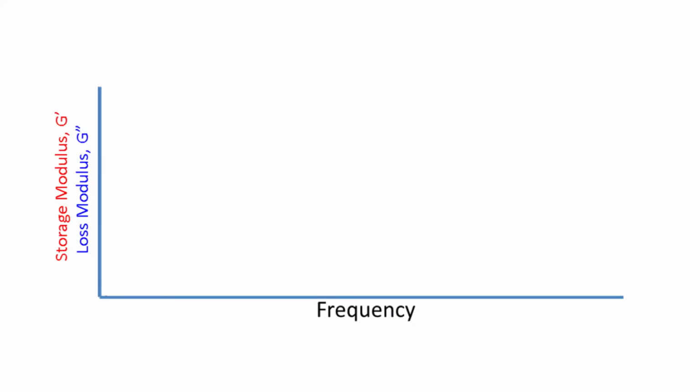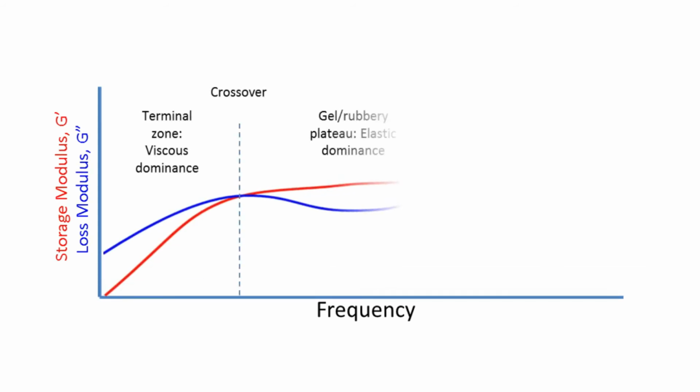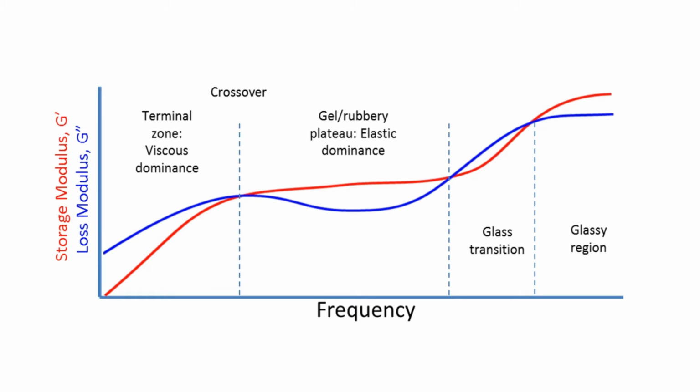So the regulatory bodies request storage and loss modulus versus frequency. In the test, the sample is oscillated at a range of frequencies, effectively imposing a range of deformation timescales on the sample. The reason they do this is that by assessing the relative relationship between the moduli across the range of frequencies, it's possible to identify similarities or otherwise that are reflected in microstructure.